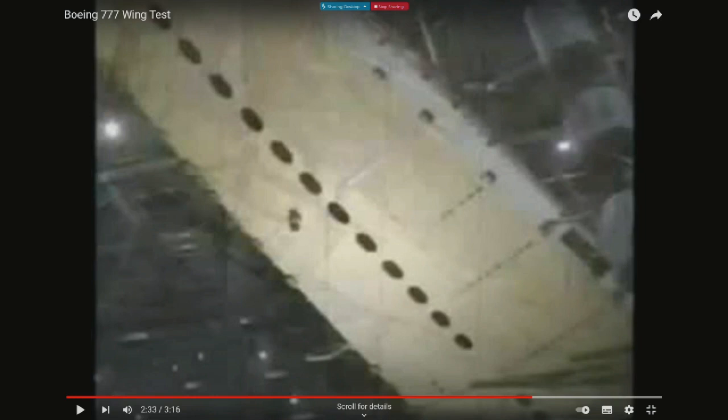Yeah, so that's a type of failure called brittle failure. You are right, good observation. It depends on the type of material you use. So these are probably some form of fiber composites, for example, which have got a brittle failure mode rather than the ductile mode that you would observe with a piece of steel. Steel will bend usually before it finally snaps, whereas some materials would fail in a brittle manner. Yeah. So the explosion is due to the buildup of the stresses.